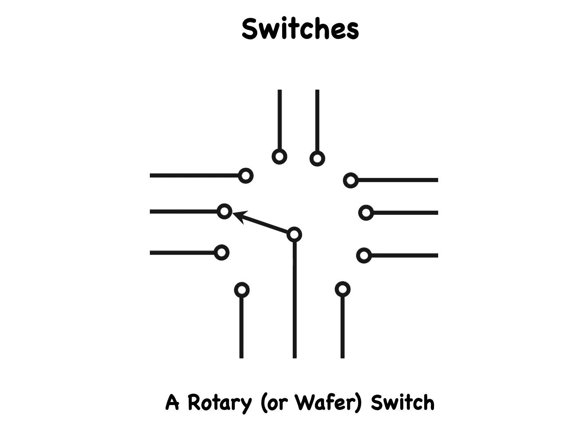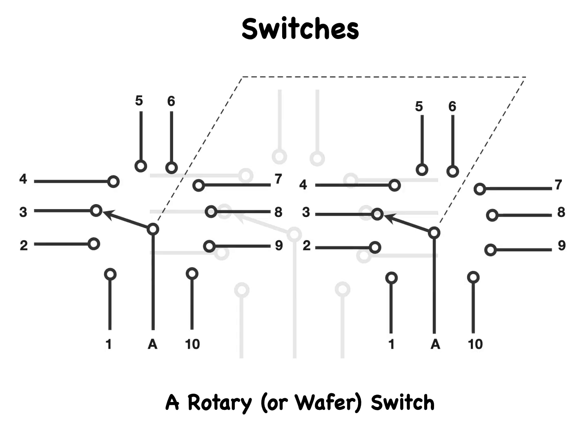Occasionally, you'll encounter sets of rotary switches ganged together. Much like 2 or more variable capacitors, rotary switches can be made to rotate in sync with one another. Here we show the schematic symbol for an arrangement that uses 2 rotary switches. The dashed line tells us that the 2 switches are ganged. The 2 arrowed lines, which indicate the throw positions, go around in sync with each other. So, for example, when the left-hand switch rests at throw number 3, the right-hand switch also rests at throw number 3.